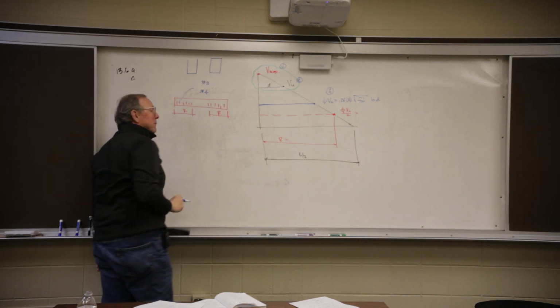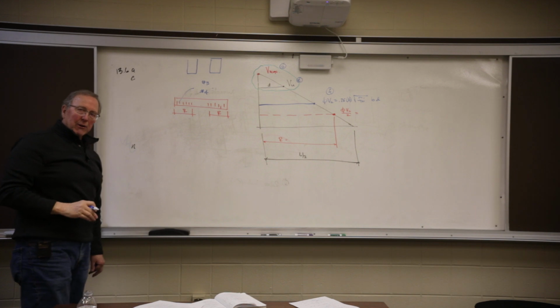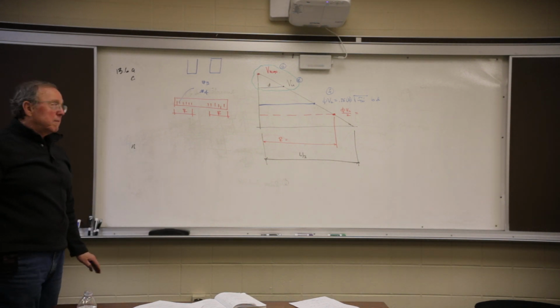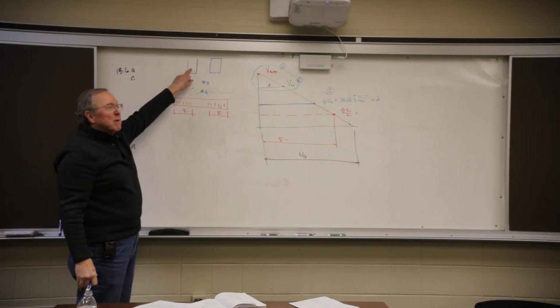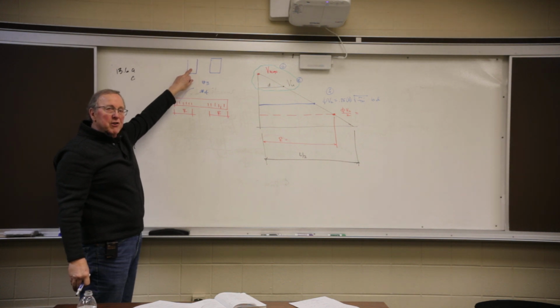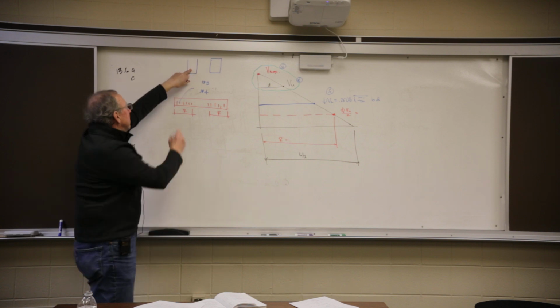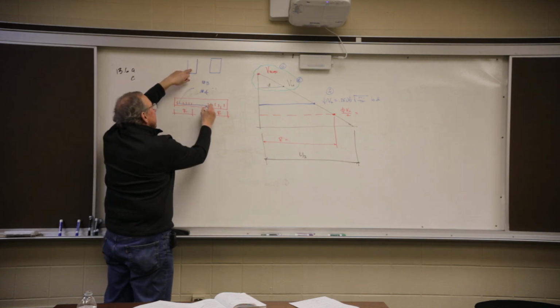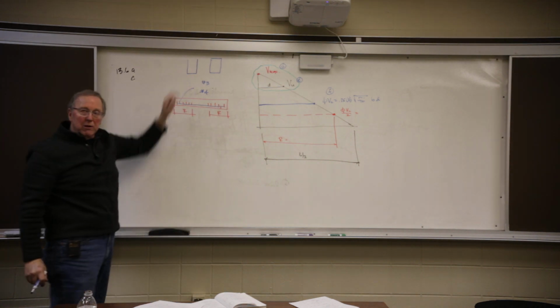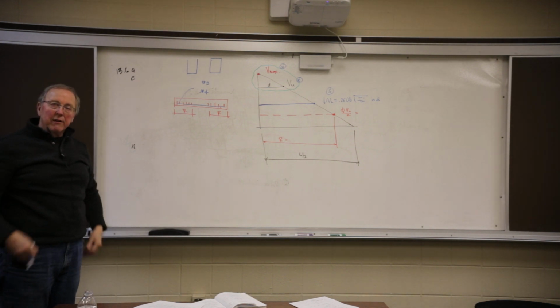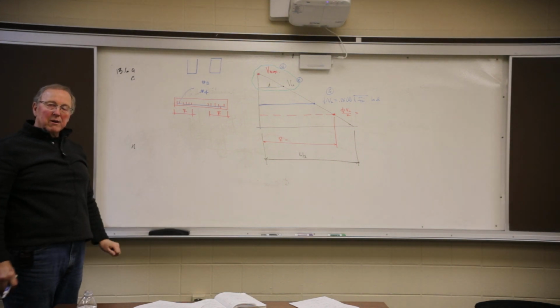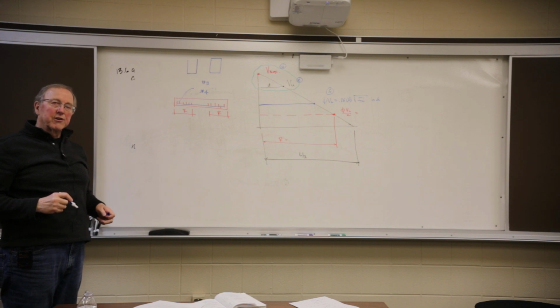So the bars have to be bent. If you get a great big bar, you can't bend them very easily. Number 3s are typically used for number 8 bars or smaller. So if my longitudinal steel going here is a number 8 bar or less, we use number 3 stirrups. If it's a number 9 bar or more, we typically use a number 4 stirrup.